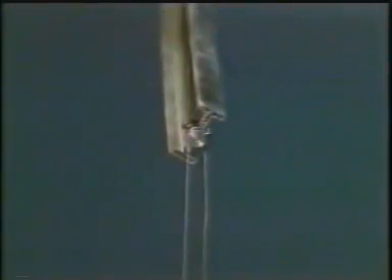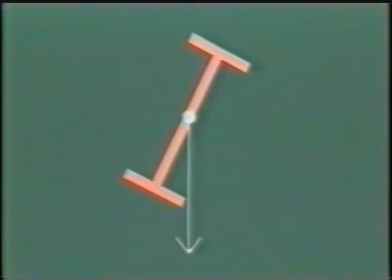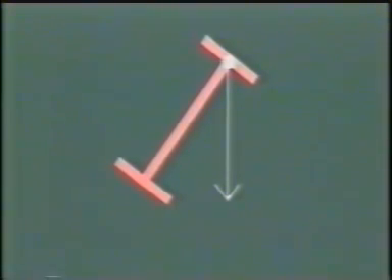One feature not mentioned so far is the level at which the load is applied. Consider a cantilever, such as one of those shown earlier, with the load applied through the centroid of the section. This may be regarded as the standard reference position. However, it can be seen that if the load is applied at the level of the top flange, then it exerts an additional overturning moment, which clearly enhances the torque and causes less favourable conditions. Conversely, if the load is applied at the level of the bottom flange, the resulting moment is tending to limit the twisting action of the section, which is advantageous in terms of elastic instability. Thus, the level of load application also has an influence on the behaviour of slender beams.